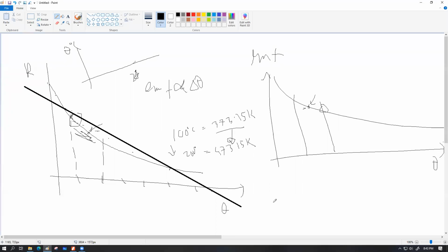Okay, sir. Think about it normally: if I increase the temperature from 1 degree Celsius to 2 degrees Celsius, I can say that in the degree Celsius scale I have actually doubled the temperature. But what would this mean in the Kelvin scale? From 274 Kelvin I am increasing it to 275 Kelvin, right? So the Kelvin temperature is not doubling here. The amount of increase is the same. The amount of increase over here is 1 degree Celsius, and over here it is 1 Kelvin. But in terms of number, the degree Celsius temperature got doubled. That's not true for the Kelvin scale because they are parallel but not the same line.